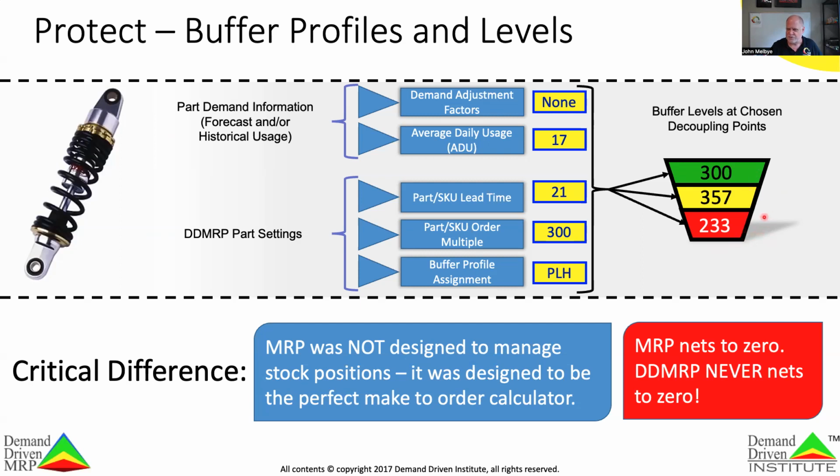And it's something that trips people up right off the bat. If we don't say that, we think this is the amount of inventory I'm expected to have, which is 890 parts for an average usage of 17, which seems a little bit nuts. So understand that that's not your bucket of inventory. That's your planning buffer that we will use to make calculations from.